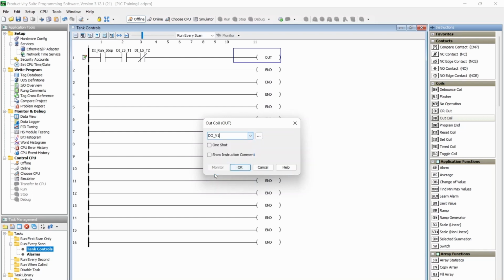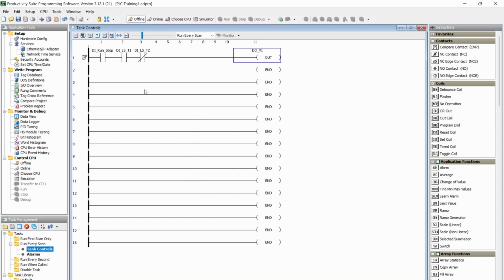So we're going to open up our valve now. So if we're in run mode, tank 1 level switch becomes true and tank 2 level switch is not true, saying that it's overfull, then we're going to open up this valve. That's really the controls to start the system.